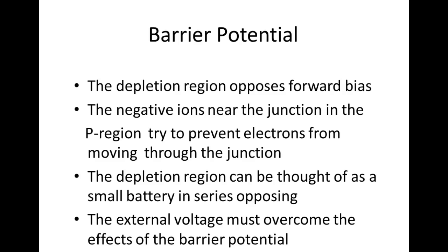So these guys still have to be heat sinked and stuff like that. You know, you think 7/10 of a volt, that's not much. But if you're conducting 100 amps of current, 7/10 of a volt is still 70 watts, right? You understand that? That thing would get really dang hot. So we usually have to mount those things on heat sinks.